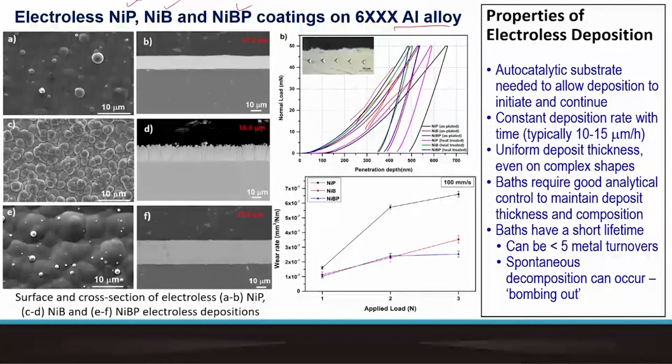And if a very high modulus, thin coating is possible on the surface, then obviously the wear rate improves even at higher load. So you are able to maintain a fairly high amount of wear resistance at even loads of say up to about 3, 4, 5 newtons.